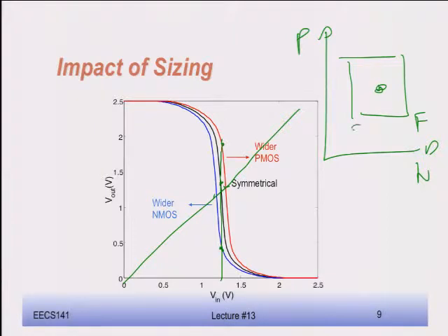For the NMOS, I can be fast and I can be slow. For the PMOS, I can be fast, I can be slow. So now we have 4 operational points that you can look at. When, for instance, I can assume here a slow NMOS, fast PMOS, or a fast PMOS and fast NMOS. This is a fast NMOS, slow PMOS, slow NMOS. These are 4 operational points, now extra points.